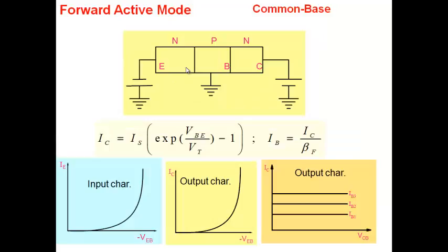All right. So whatever I've been describing for you so far is forward active mode and saturation, and I've been talking mostly in the common base configuration, where base, as we said, is constant, and emitter base junction forward bias. If this is reverse bias, we are in forward active mode. If this is forward bias, then we are in saturation mode. And these are the characteristics that we get.